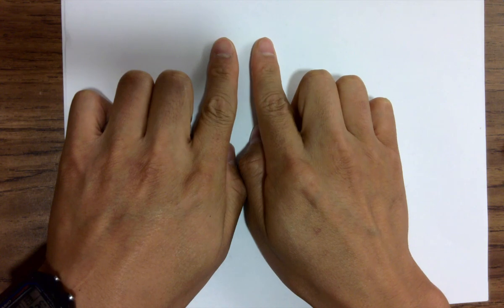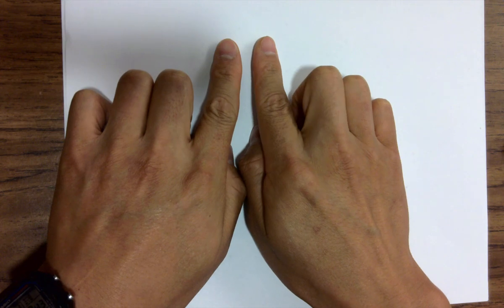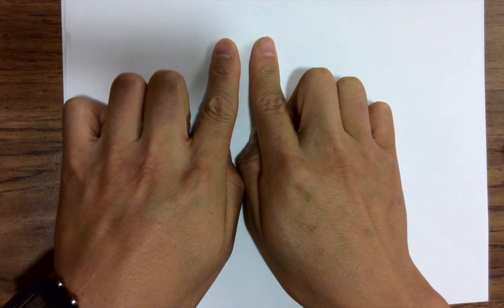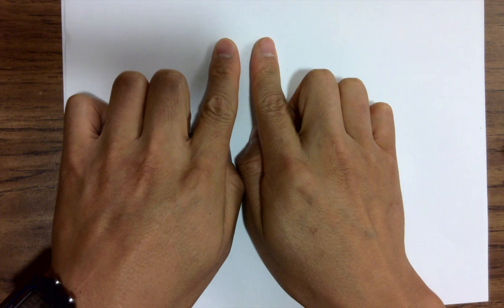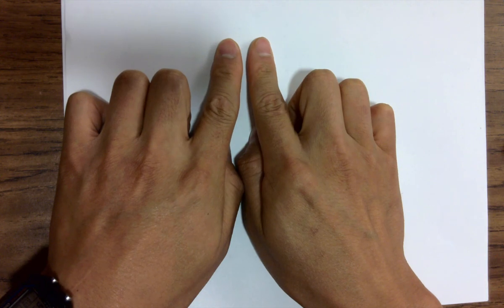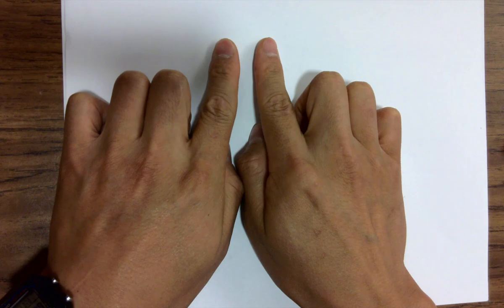It's basically defining the spaces between different traces within the same layer, like metal 1 to metal 1. If you place them too close to each other, the fab's manufacturing process, or that technology process, like 500 nanometers, is not able to resolve that gap. Then you have to place them a little bit farther apart from each other. So that's the design rule.